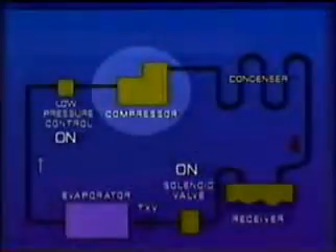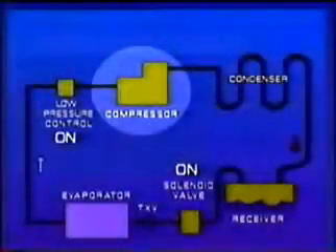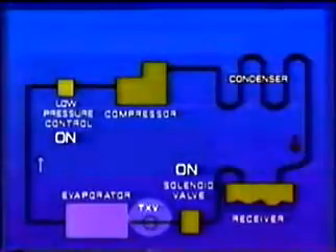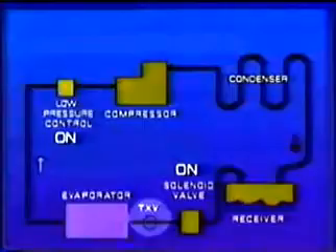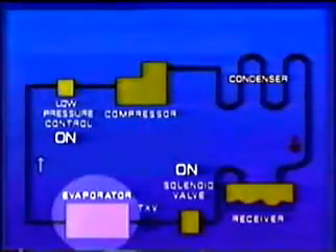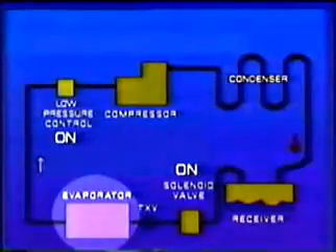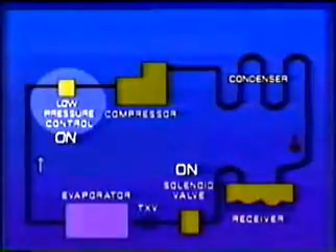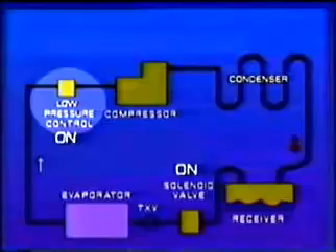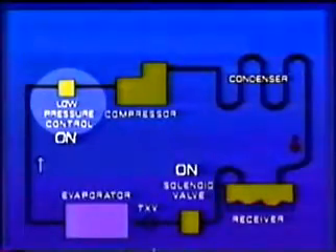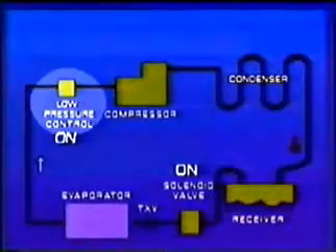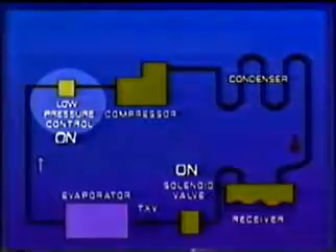Watch for undersized evaporators or oversized compressors. Check for plugged dryers to be sure a solid column of liquid can enter the thermostatic expansion valve. Set the valve to a minimum practical evaporator superheat recommended by the fixture manufacturer. Keep the pressure drop in the suction line to a minimum and still maintain sufficient velocity for proper oil return. You can reduce discharge temperature faster by raising suction pressure than by any other means.